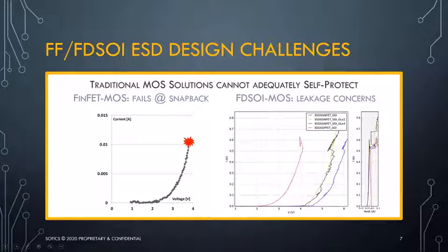First of all, it may not be very visible, but we're basically talking about microamperes of leakage, which is very high for an ESD protection device. And in addition, when we look at the NMOS devices, we see this disturbing trend here, that leakage is gradually increasing in the very low stress levels. Now, obviously, at the higher levels, something more dramatic happens, and this is definitely very hard physical damage.